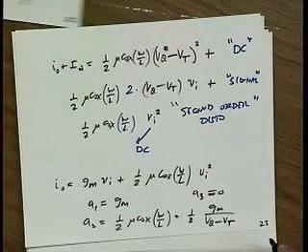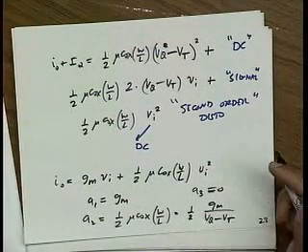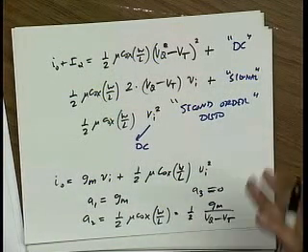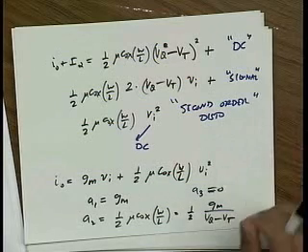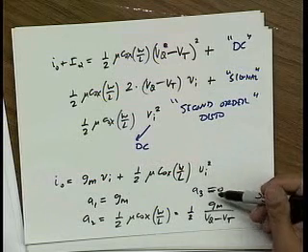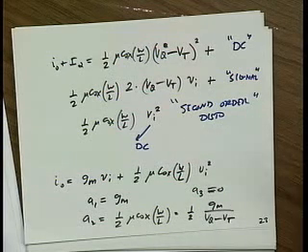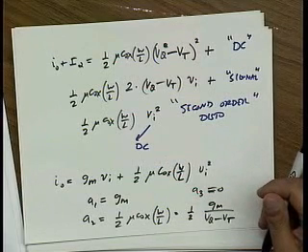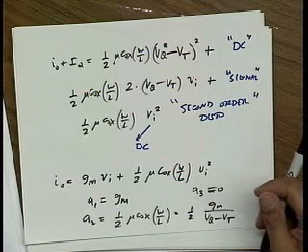Now that's really good if it were true, because remember all the IM3 I talked about, all the gain compression, all the blocking characteristics, all that came from third order. So an ideal FET would be a very ideal device. Now, could someone tell me why in real life things aren't so good? What mechanisms do you think could lead to maybe some third order distortion? Okay, channel length modulation, very good.